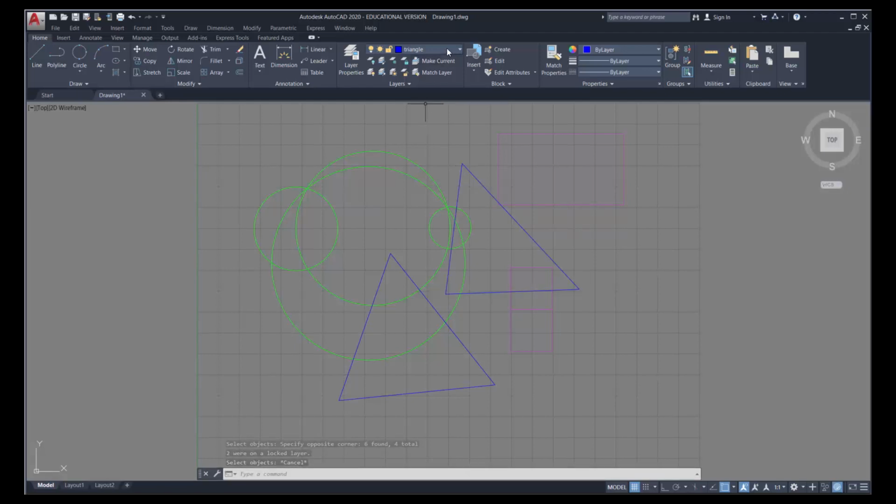That brought me back. So you can see that these functions in the Modify menu, and we haven't learned a lot about them, but these functions in the Modify layer have no effect on the actual objects that are on the screen in relationship to what layer is current. Copy is always one of those that one would think that it is affected by the layer, but that's why it's in the Modify menu. So when I copy an object, it takes on the properties of that object regardless of what layer I'm in.